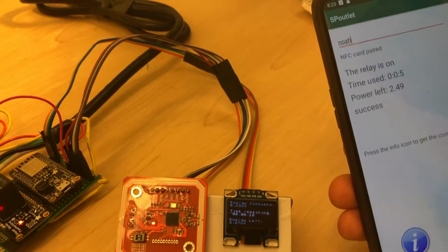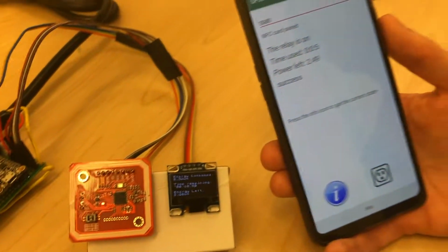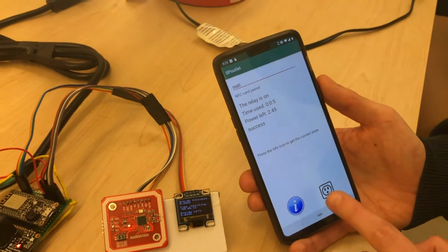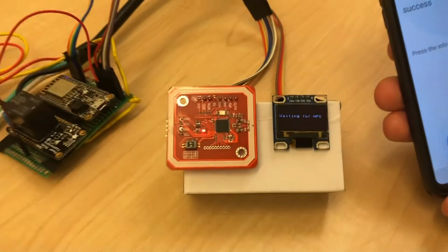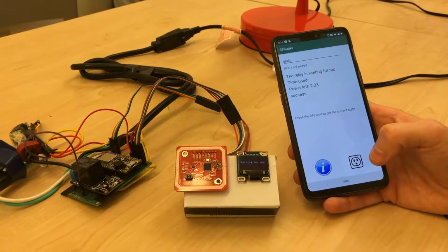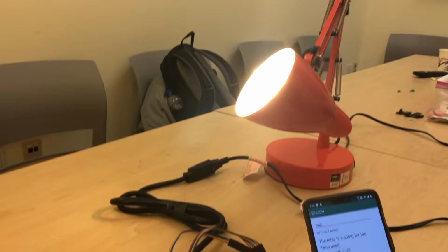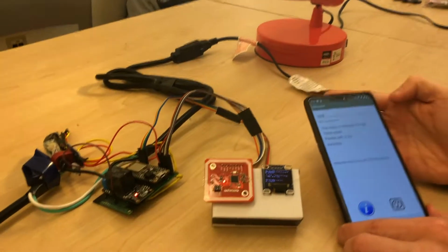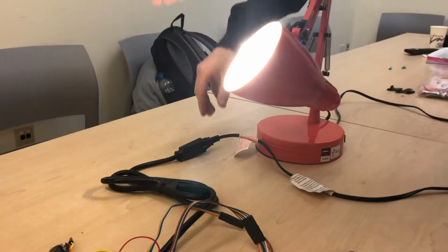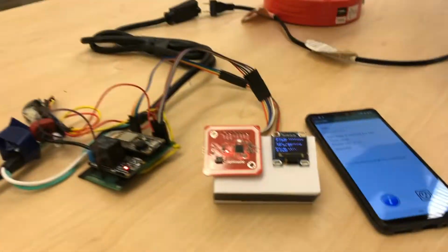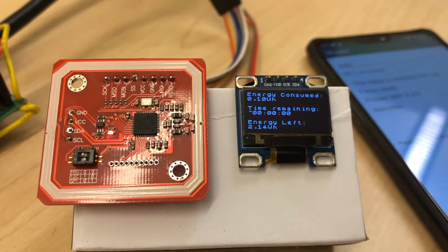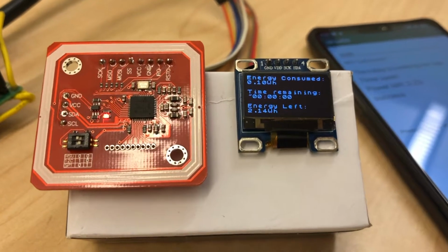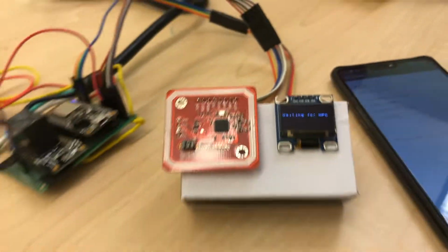There are 3 ways to turn off the device. 1, the user can turn it off manually from the app. That turns off the device and unpairs from the account. Another way to turn the device off is if somebody unplugs or turns off the device for a 10-second period. The outlet will recognize that the energy being consumed is not changing and that the energy drawn at any given time is 0. After a 10-second period, it will turn off and disconnect from the user.